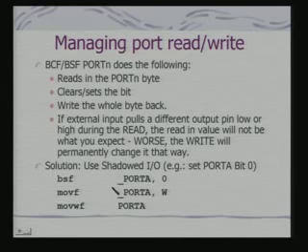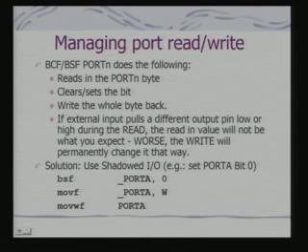Now, there is another problem associated with the code. Let us look at this. Read, modify, write instructions enable us to implement the critical region, but there are also some issues involved here. Just imagine that you have read and then there is an external input which pulls a different output pin low or high during the read, because read takes some finite clock time. So, the read-in value will not be what you expect. In other words, the write will permanently change it that way, okay, because after the write the port bit values would be changed and it would be changed permanently.